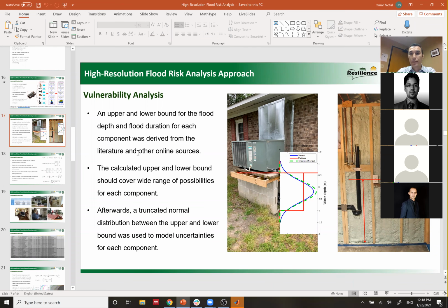Okay, so essentially, when the flood depth touches the height of the air conditioner, it is treated as completely failed, right? Yeah. What I'm trying to do is compare it with seismic, where we define the damage states depending on the structural drift of the building. For example, if it is within some particular drift, then this is a damage state. I was wondering if there is some kind of analysis for flooding. Yeah, each hazard has its own nature and approach.